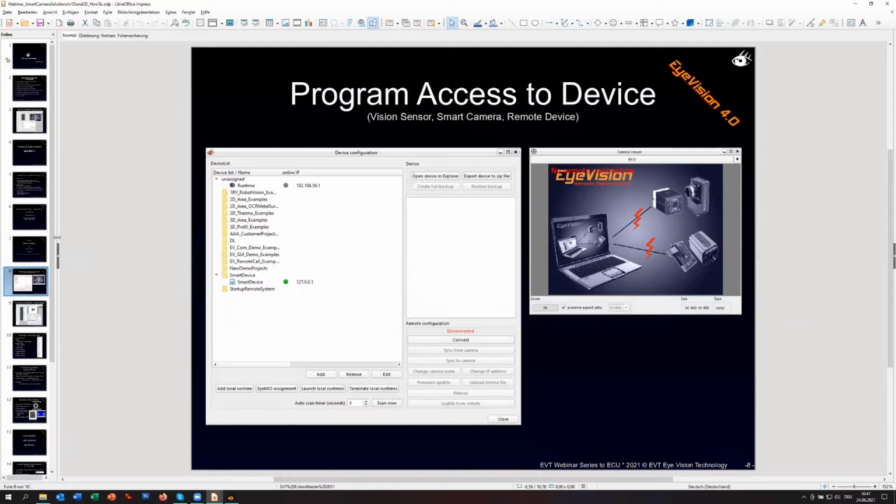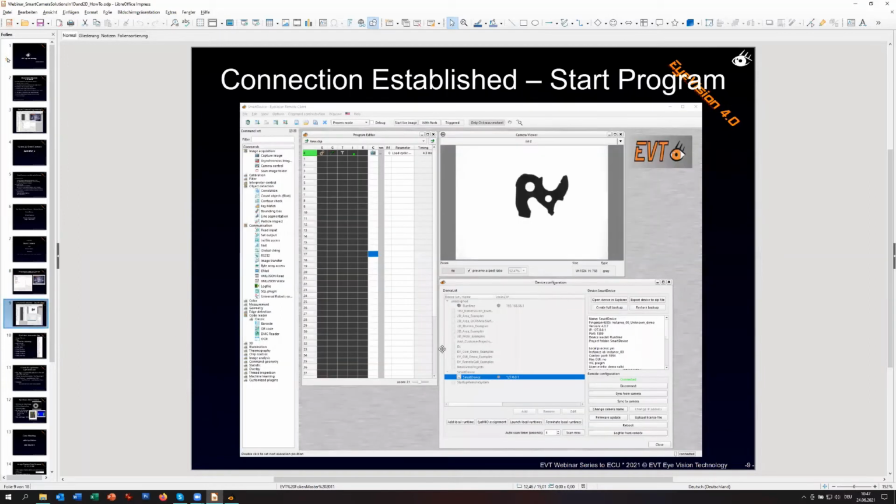Of course, if you program it, you need the information from there. So you have to display what the camera sees. That's why we have this remote interface, and we can see the image data as well as the I/O lines. And if you have an RS-232, you also see the results of the RS-232 communication on the programming front-end user interface.